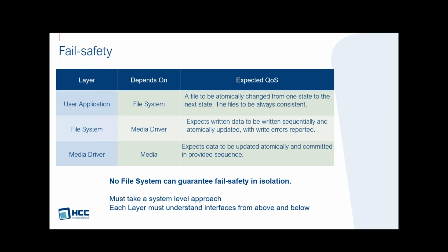This means that they don't know what they have to do to guarantee fail safety. And equally, there's no clear specification from these file systems of exactly what is required from the media drivers, so that somebody doing an integration process can make sure that the NAND flash driver matches the file system.